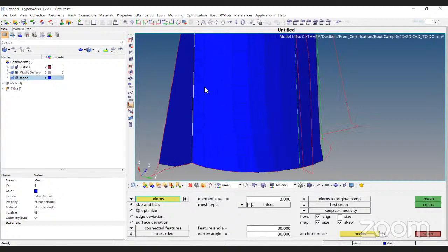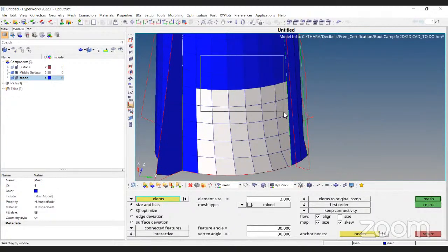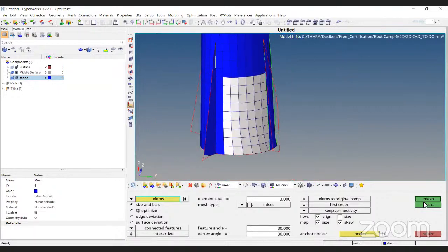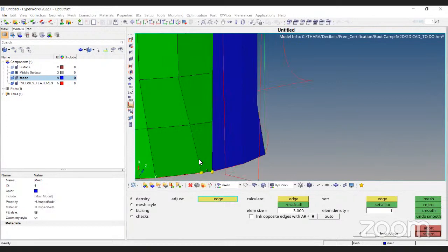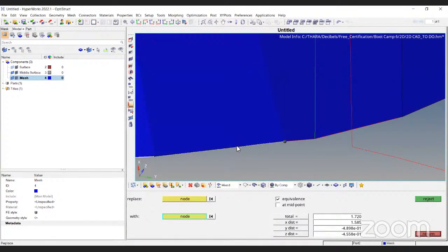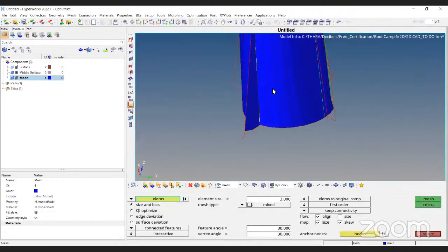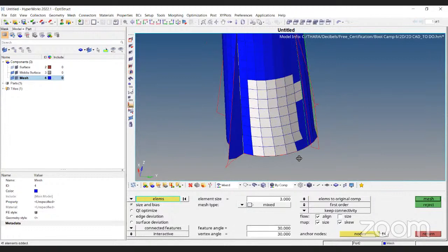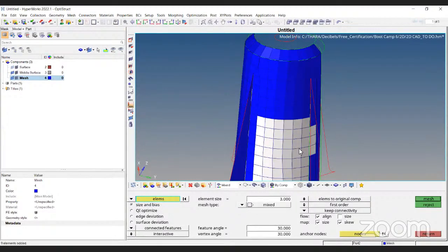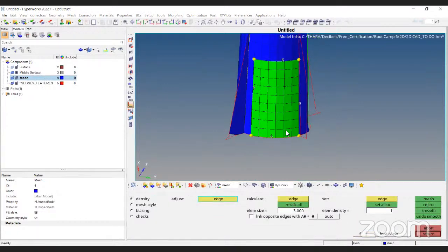And if you see here the mesh flow lines are not correct, just go and select this one. Mesh flow means the elements you are going to create should be very clean elements. So you just replace this node to here and again go to F12. That is for the mesh addition. Either you can go by selecting the window or select element to element also. Say mesh. See, now it is done.